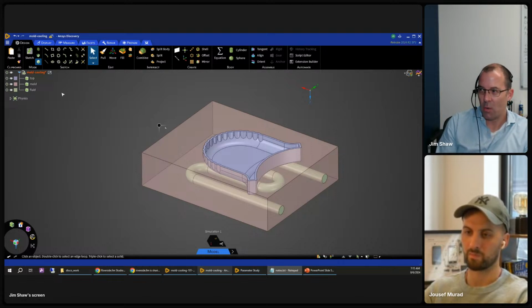And sometimes if you're doing a lot of top-down design, in mold design and plastic design, a lot of times we're doing surfaces and curves, and driving our solid geometry from other geometries. Think about a large team of people. One person owns the industrial design, that's the surfacing, and then other people, the engineers, are more concerned with the physical stuff. So you've got this CAD file that's crazy. It's got edges, surfaces, and solids, and a lot of times that's not nice geometry to bring into a STEP or IGES file and then into another CAD.